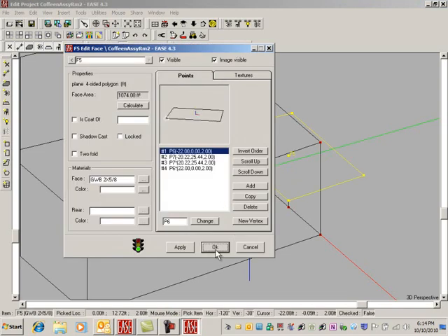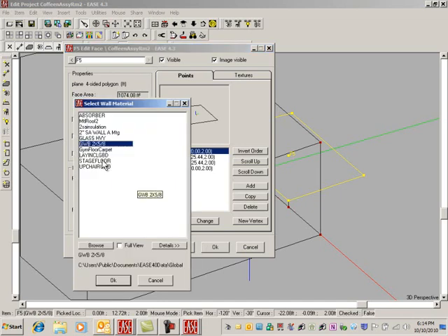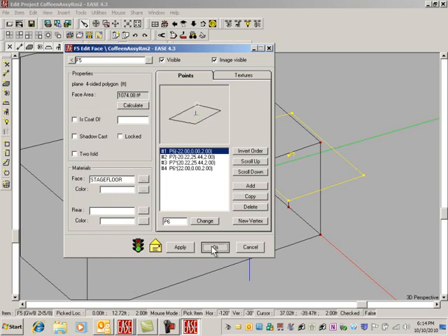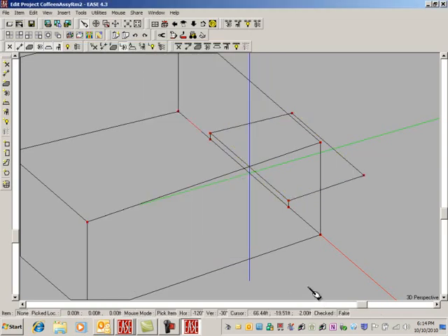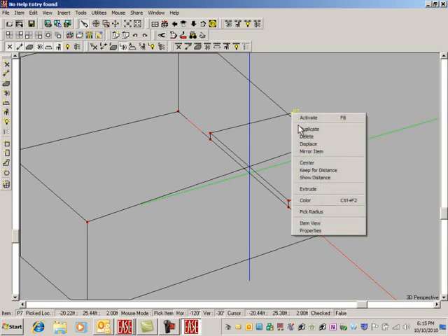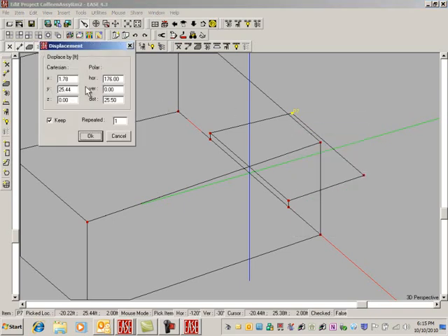But what if we know where this guy is? Right there. And if we wanted to cut this wall, that's at minus 22 in the x direction. We don't have a face here, but we know that that vertex has to be here in the roof if we're just going to make this little proscenium wall. So again, we could go to this business of vertex on face margin. And here's our vertex.